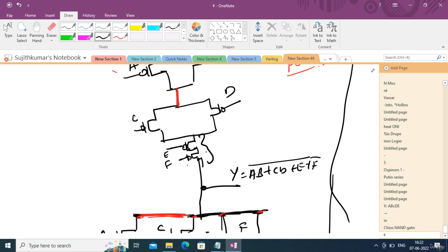So that's how you convert any Boolean equation into a complementary CMOS circuit. What you have to do is design this, and you can simply take the transistors and arrange them in this manner, and you can easily fabricate an IC, right? Again, fabrication in the sense of the design part. We cannot fabricate it standalone. Some support is needed from the industry. You can only do the design.